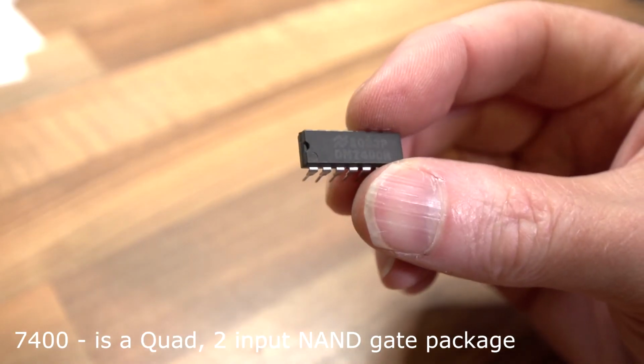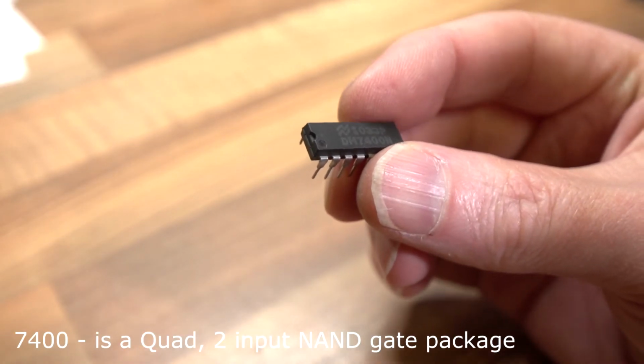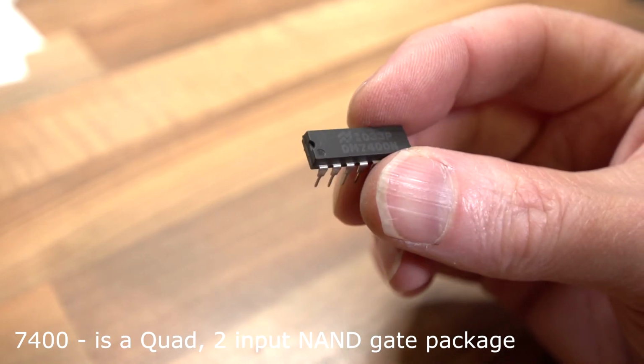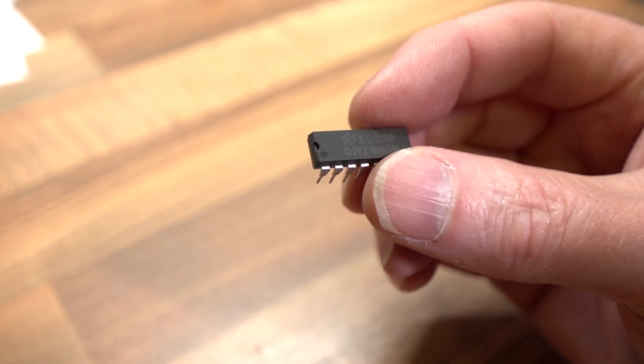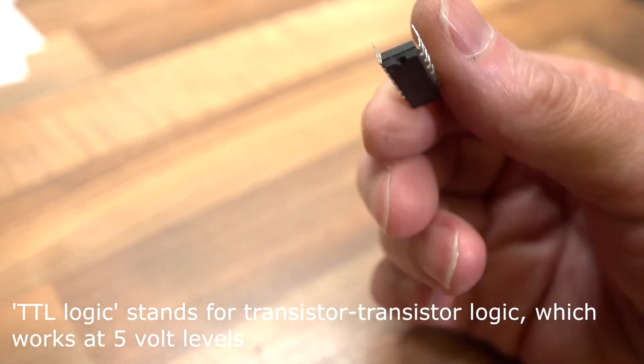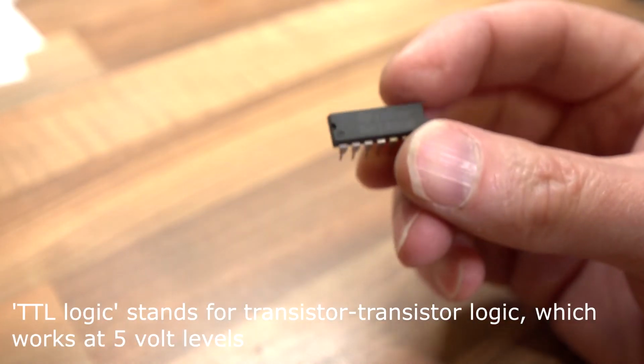And this particular one is a 7400. It's called a 7400 device. That's a TTL. The full name is a quad 2-input NAND gate. In other words, quad, 4 of them, 2 inputs for each NAND gate. So you get 4 in 1 in one of these.